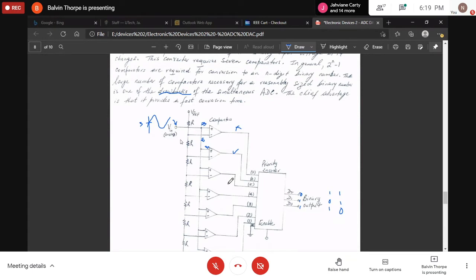I'm showing you now that the operation amplifier from last week can be used to do some other things. Just to be theoretical in terms of coming up with analysis and equations, I'm showing you that in the real world, you can have the operation amplifier being used to convert a sinusoidal wave to a square wave through the comparator. Show you how the comparator works.